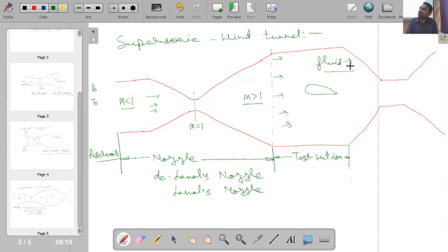Here flow velocity will be very high. So when very high flow velocity goes outside, across this complete device the change of momentum will be very large, and it will create a large amount of thrust force in the leftward direction. So to hold this structure, in order to provide the structural rigidity, I have to provide a very large amount of force in the opposite direction.